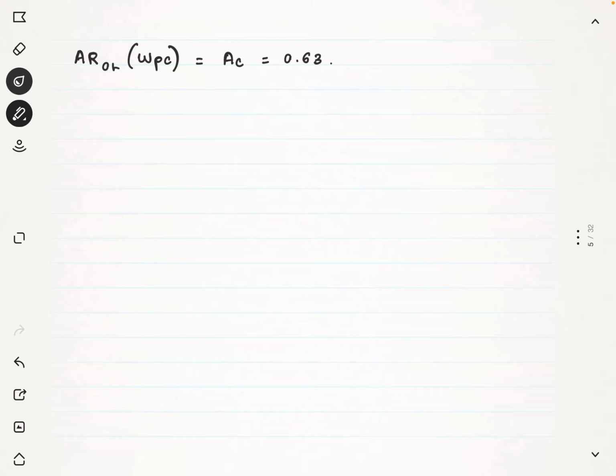So here the critical amplitude ratio is less than 1, so the closed loop system is stable. So this is how we'll be doing the stability analysis through the frequency response analysis route using the Bode stability criteria.